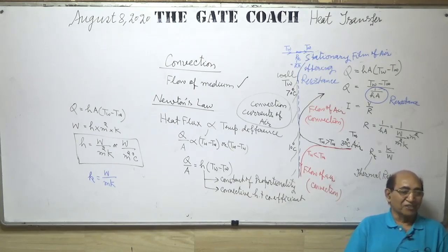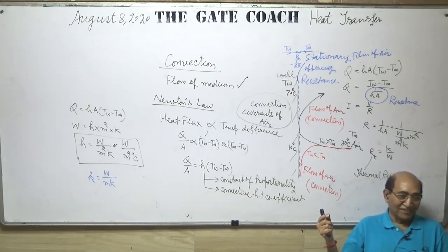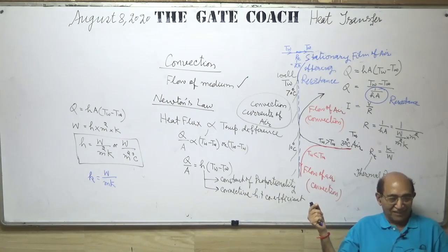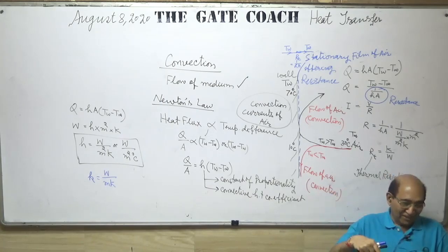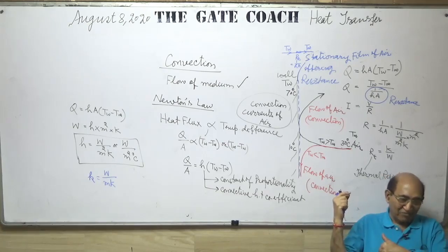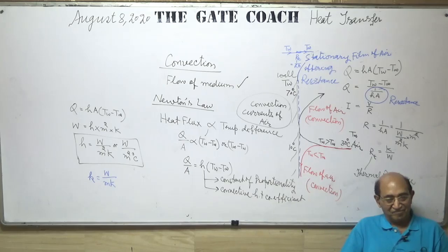And heat transfer is similar to that of conduction, because when the medium is stationary, it is like conduction. So that is the reason I stated that this phenomena of convection, when studied deeply, can be called as conduction, and that is why I am here writing the expression for the resistance, 1 upon HA.